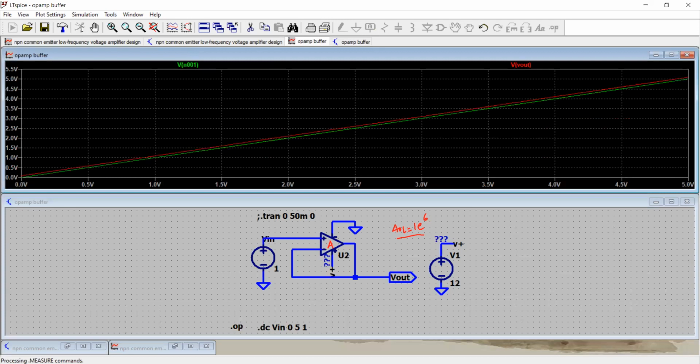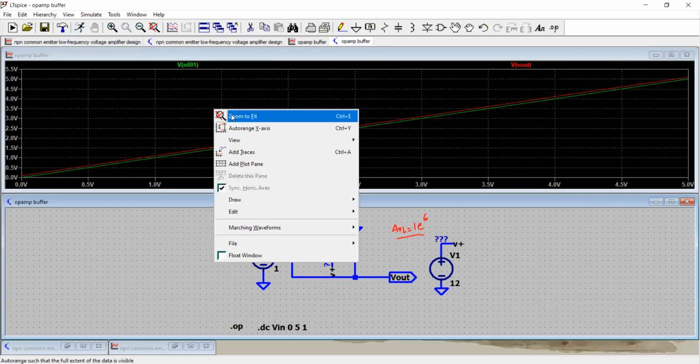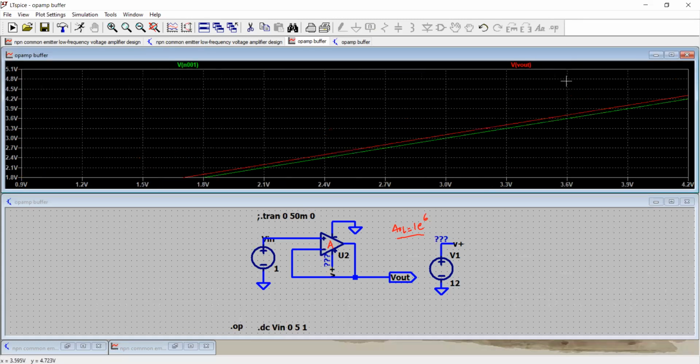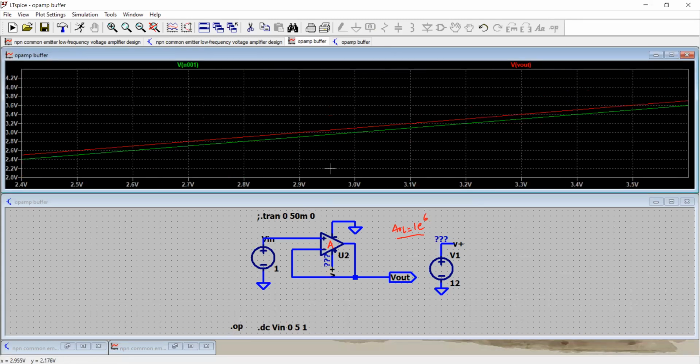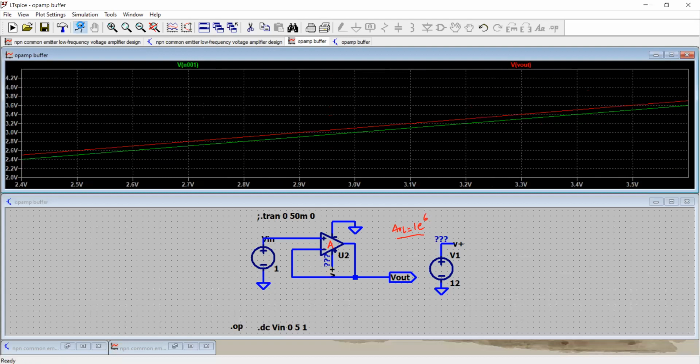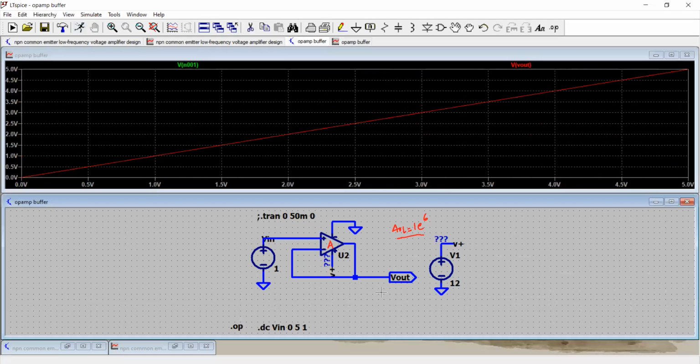So now it's clearly a voltage follower, but no longer an exact voltage follower. So in a practical op-amp, when you build circuits, you will have such situations, where output is not exactly equal to input. So go back and keep it like what it was, 0, right here, and then click here. And that's good, right?